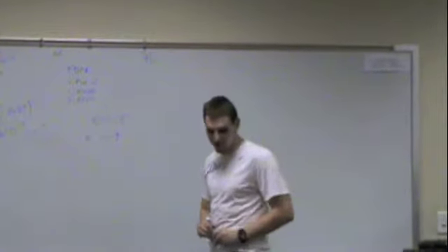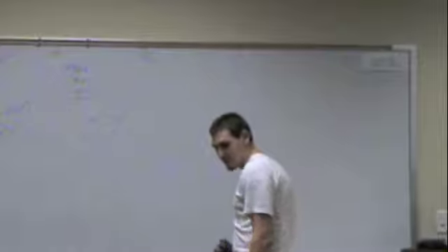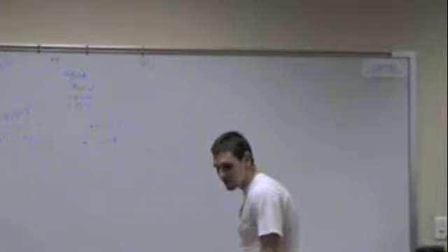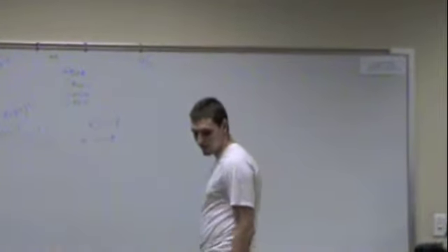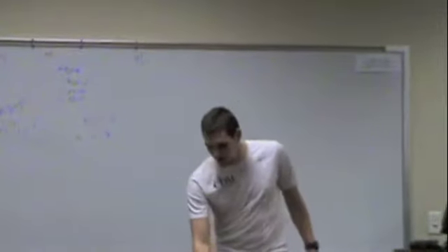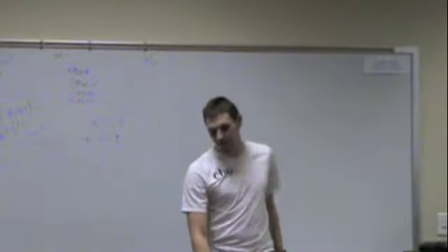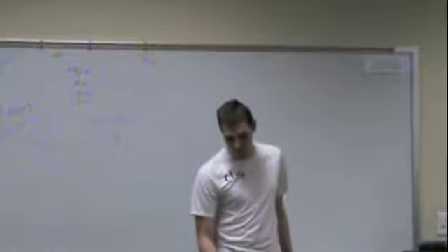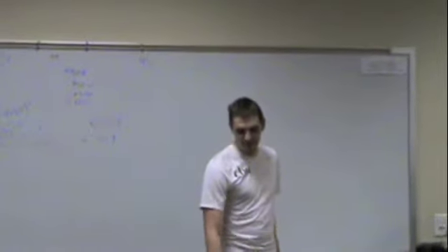If you want to know what 45 is, a silicon crystal is 5 millimeters long and has a rectangular cross-section of 20 micrometers times 40 micrometers. The donor concentration, Nd, at room temperature is 5 times 10 to the 15 centimeters negative cubed. A current of 2 microamps exists in the crystal.